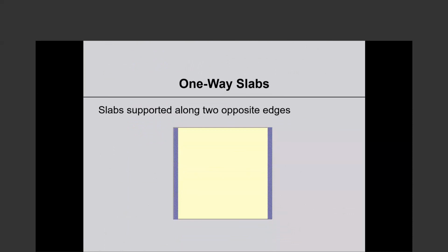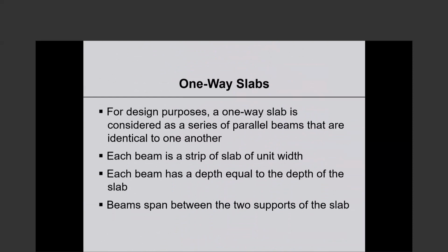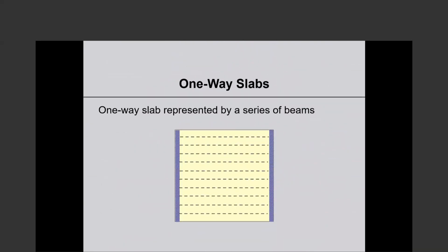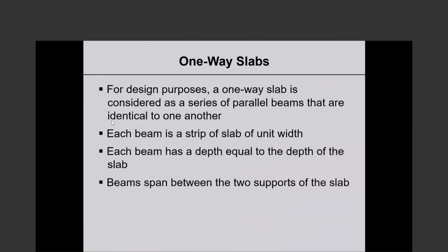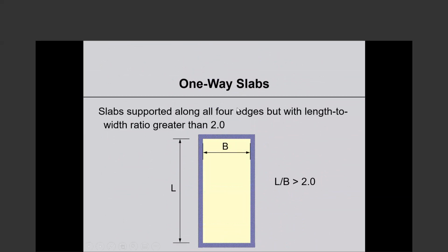Now I have a one-way slab, and I am thinking that time is out, and this is easy material. I think all I need to point out is that, let me say a couple of things. If you have a beam supported slab, beams on four sides, this slab will bend in both directions, in the short direction and the long direction.